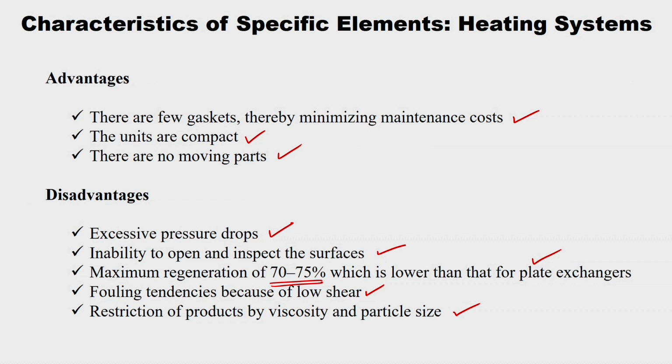So viscosity is two-way, right? One is the liquid itself having high viscosity, or the particulates suspended in the liquid increase the viscosity. So all three of these exchangers, double pipe, shell and tube, and plate type heat exchanger, are best suited for pure liquid products, or products with particulates of minimum size or a minimum number of particles. Only in that situation are these three exchangers best suitable.